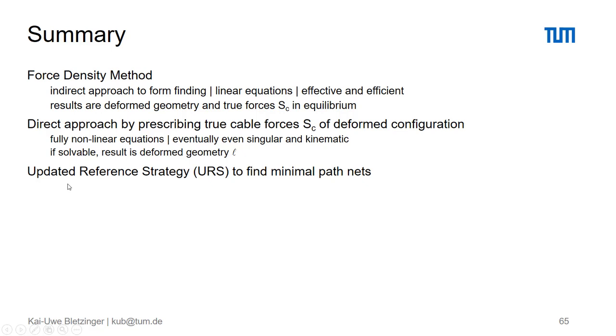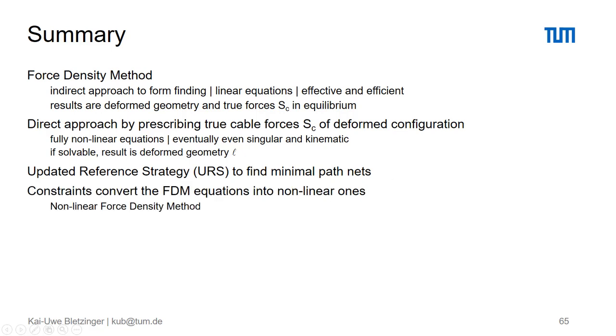We have learned about the updated reference strategy as a further alternative to find solutions with prescribed cable forces, and in particular to find minimal path nets. We can say that constraints convert the force density method equations into nonlinear equations. That's the entry into what is called the nonlinear force density method, also already introduced and defined by the paper of Schek in 1974.